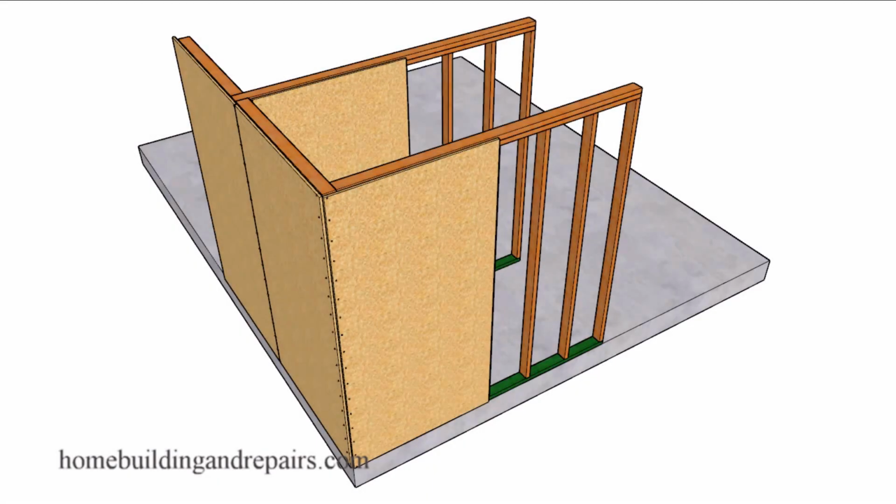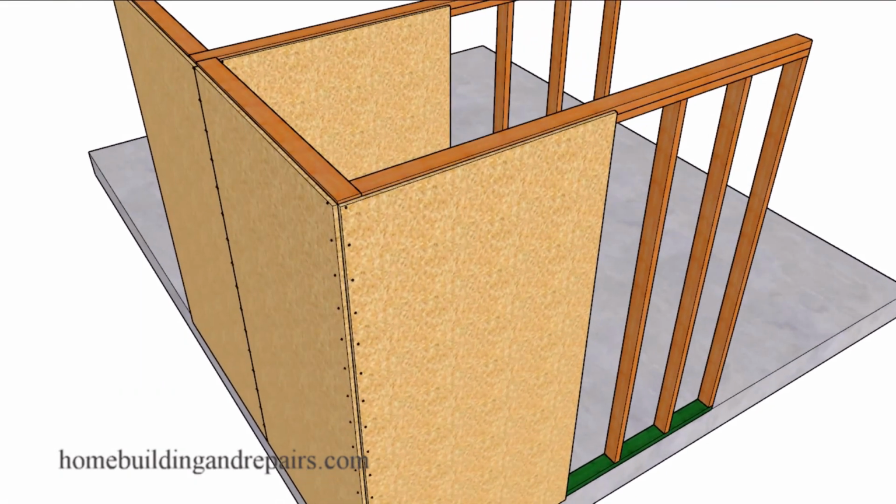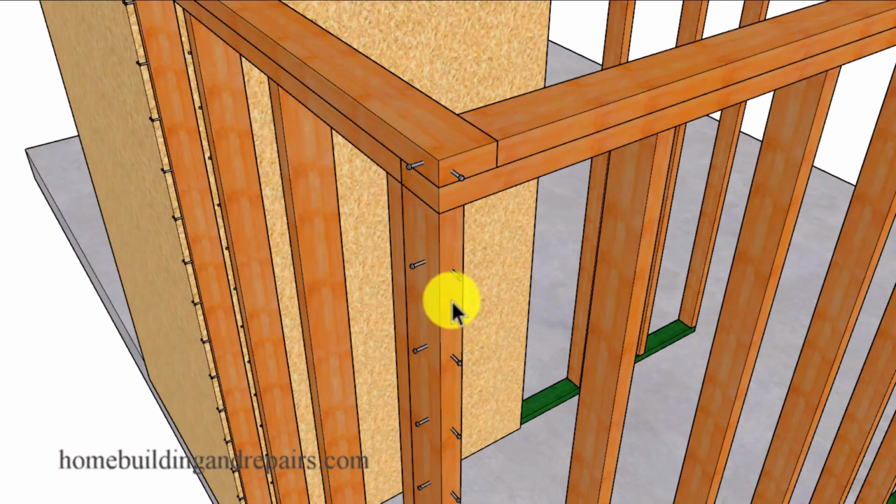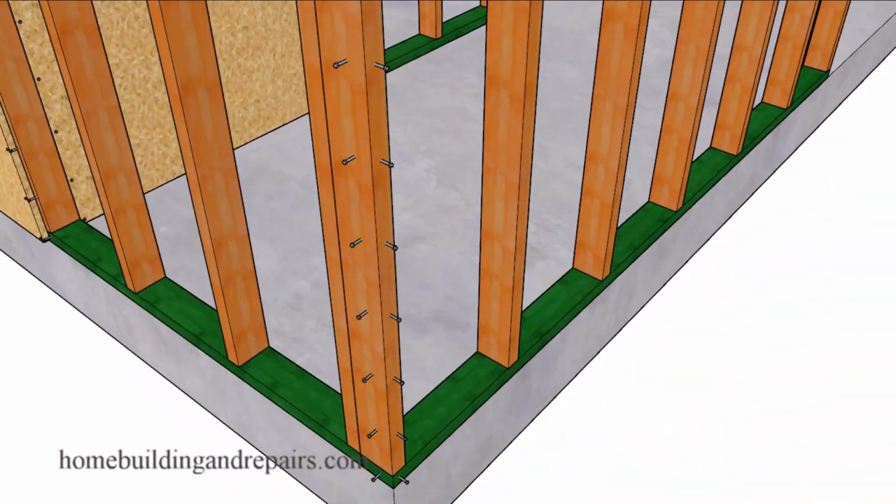Here's something that most engineers understand, and even some builders, when it comes to connecting two corners with shear panel or even exterior sheathing to create a stronger bond. So let's go ahead and take a look at the first one here, just a regular 2x4 at the end. And this situation here might have 3 2x4s right next to each other to provide you with drywall backing for the inside. And you can see here how the nails are going to be used to attach the shear panel to the framing stud. So here we just have one framing stud.